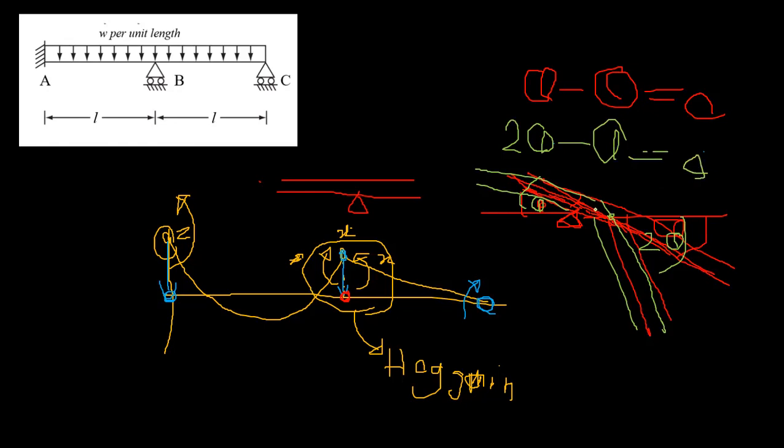So the moment you put a hinge here, the beam is not continuous, right? A continuous beam cannot bend like this. It keeps the continuity even while rotating, right? So that relative rotation is always 0. Remember the term relative rotation, okay?